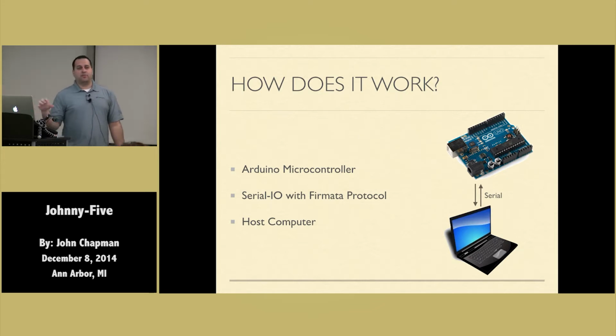So to run Johnny-Five, it relies on another computer, a host computer, to run that logic. And then the way that they speak together, they do that over serial communication, and that protocol is known as Firmata. So Firmata is a protocol that says, how do I control hardware pins via a serial protocol? All right? And as I mentioned, you have the host computer. So in this particular case, all the programs we look at will be running off of this Mac, and then it'll be calling over serial Firmata to the Arduinos that you'll see over here.